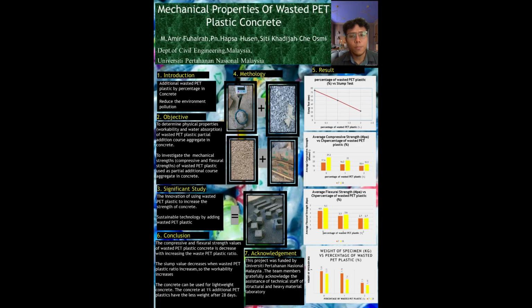The 54 samples we use to test water absorption, flexural strength, and compressive strength. Then we get the result. For the methodology, we must cure the samples for 2 durations, 7 days and 28 days. Then we move to the result.